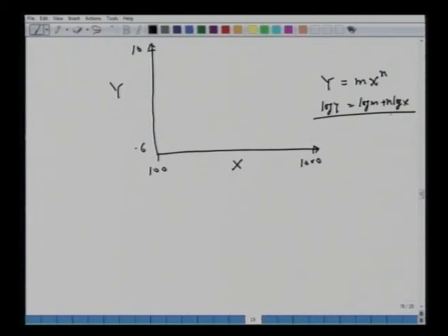So on a log plot, this line will be a straight line. So essentially, you have the data points which are fitted by the Freundlich isotherm. From this slope and intercept one can calculate. You will see that n, the power, is 1.66 and m is 8.9 times 10 to the power minus 5.